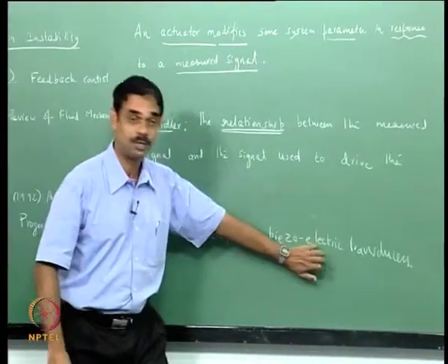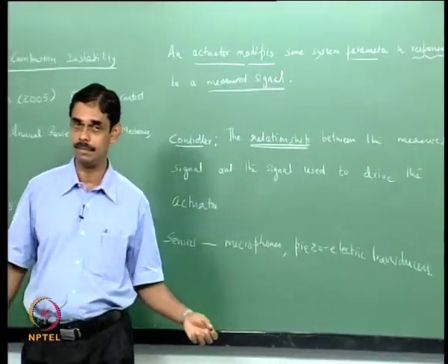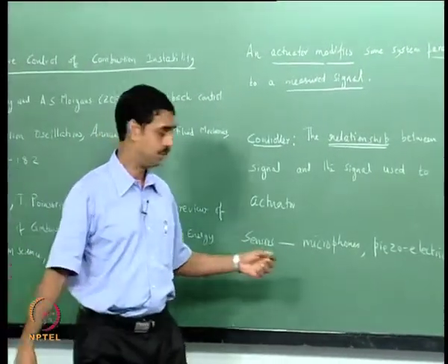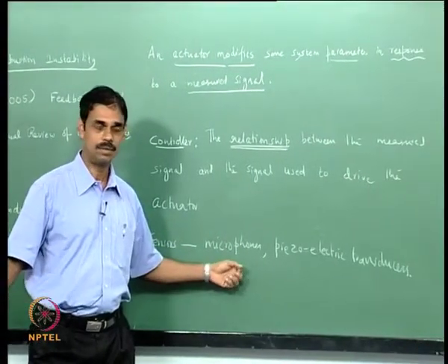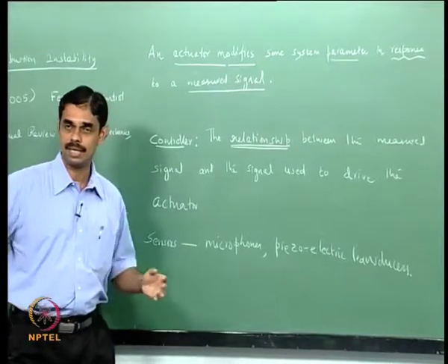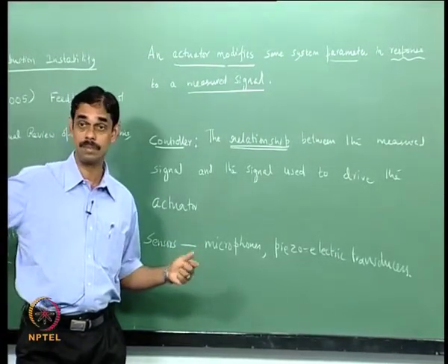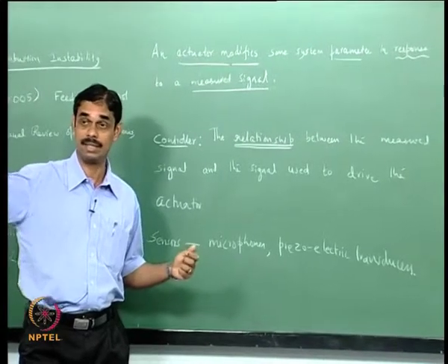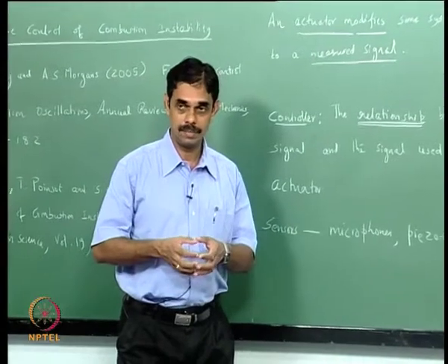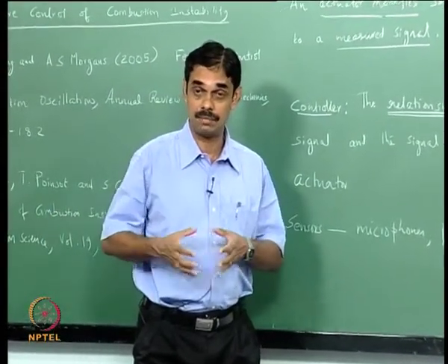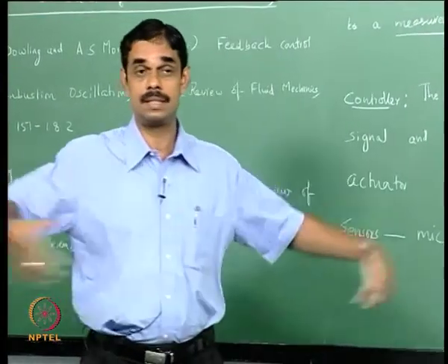Piezoelectric transducers are more robust, but there are microphones which will take 180 dB or 165 dB without breaking. So if you are careful you can use a microphone, but it is very expensive. We do not need microphones because microphones have very high bandwidth. Condenser microphones can measure sometimes 20 kilohertz or even 80 kilohertz. The aeroacoustic people use that because many times they measure a small jet which has very high frequency and then scale up to a large jet.